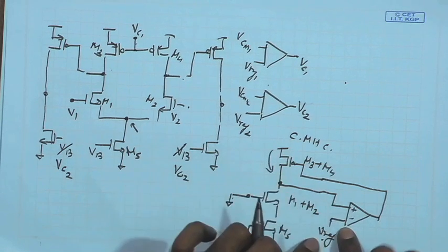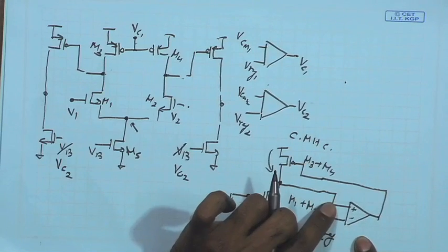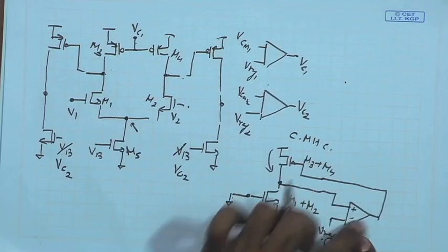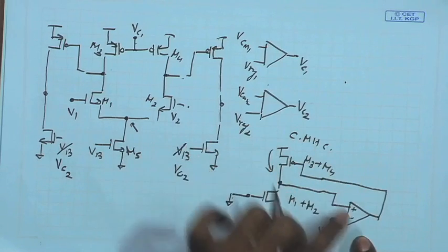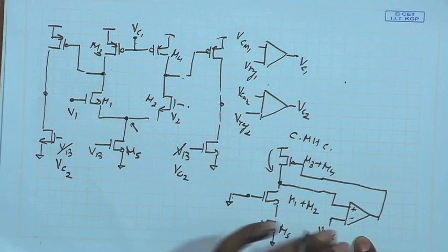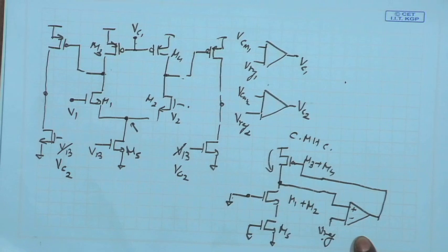As a result, we can say that there is a series feedback at the input terminal of this amplifier. Whenever the feedback signal coming from the loop is at the opposite terminal of the differential amplifier, it basically effectively subtracts from the input signal. As a result, we can say that there is an effective negative feedback coming over here.